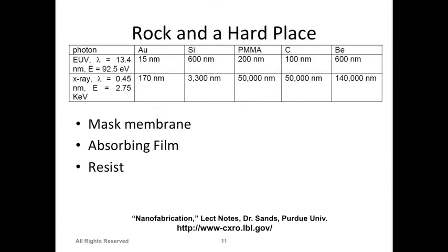What is PMMA? PMMA is a polymer, polymethyl methacrylate, something like that. It's used also as an E-beam resist. This is X-ray, but PMMA is used for E-beam. I know at least that it is being used there as a resist. It means that when you have exposure of E-beam, it's a polymer, so it breaks down from that area, and it can be developed like we have a regular photoresist. And PMMA is also present in the form of plastic sheets, so it has a different form. So the regular transparent plastics we see, many of them are PMMA based.